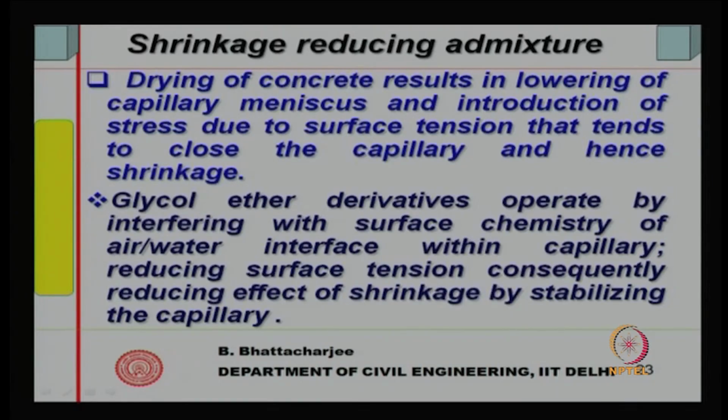Now, glycol and some of its other derivatives, for example glycol ether derivatives, operate by interfering with the surface chemistry of the air water interface within the capillary, thus reducing the surface tension and consequently reducing the effect of shrinkage by stabilizing the capillary.